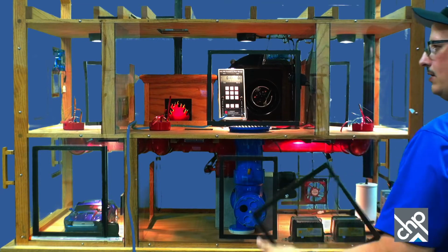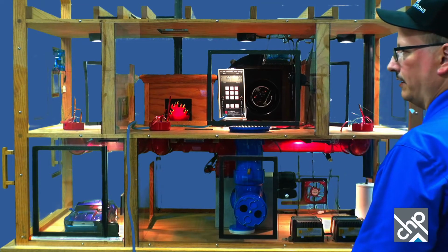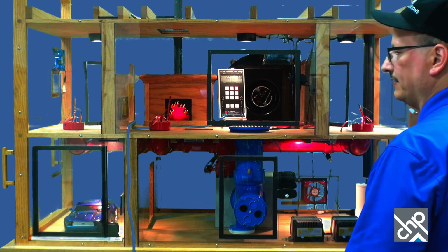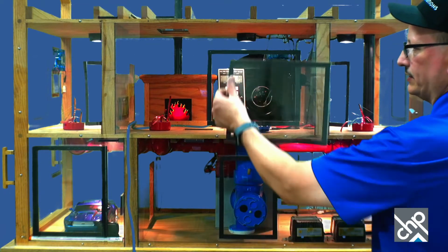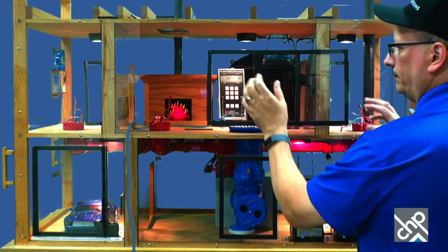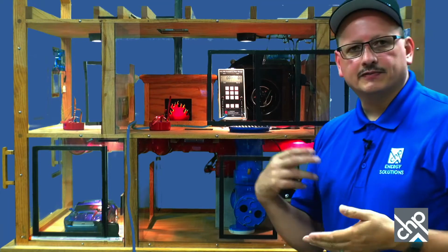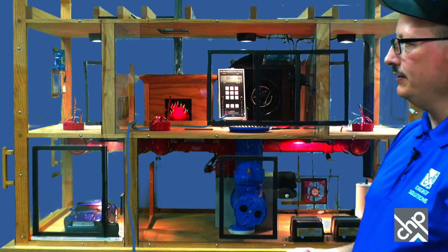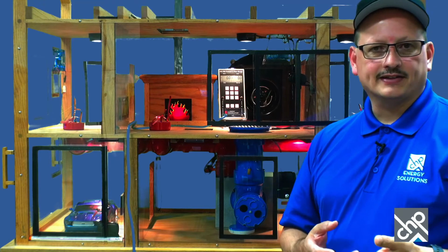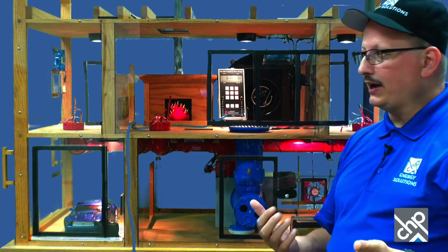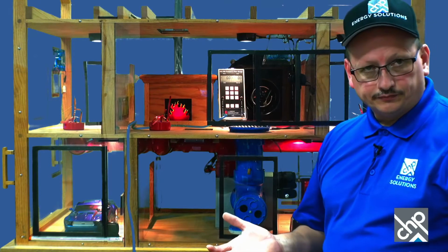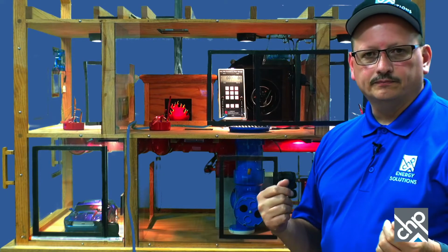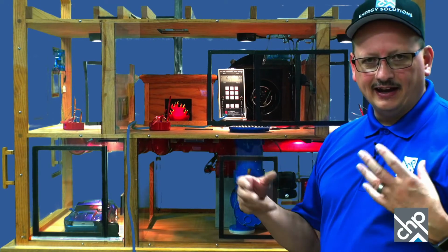You'll see that come on, and then I'm going to turn on the kitchen fan next. But what I'm going to talk about here is I've got this window off, first of all. The window's off, and so the smoke's going out the chimney pretty easily. I'm going to turn on exhaust fans. Like I say, if they're sucking air out, they've got to bring air in from somewhere else. And in this case, the fireplace is kind of that indicator of that.